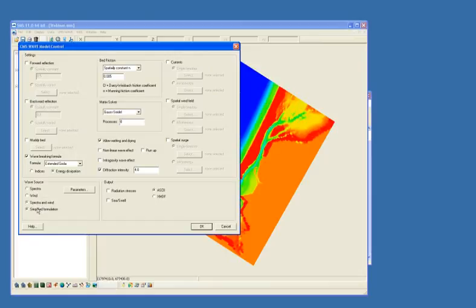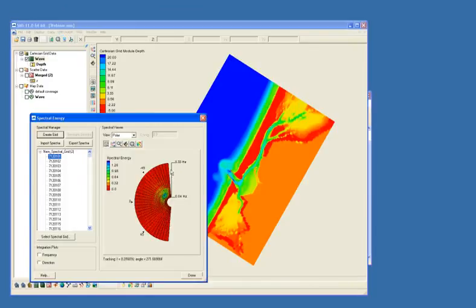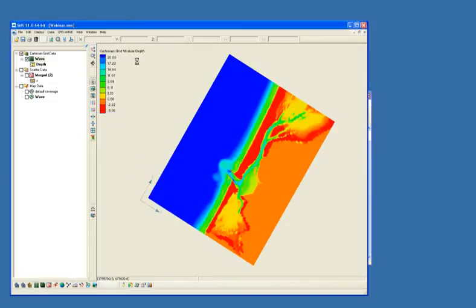And then you can also change this to a simplified formulation that changes the gridding from the spectral energy gridding from this 30 by 35 grid down to a 7 by 5 grid. So you're kind of making it a little bit more efficient by reducing the number of bins that it's got to go. But it's a much faster answer, but it may not be quite as accurate as needs to be.